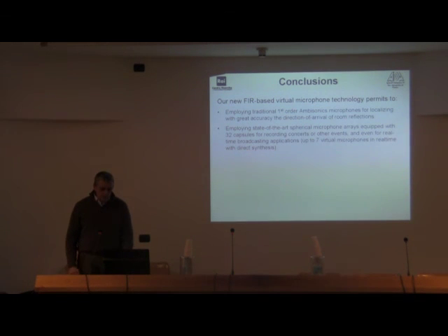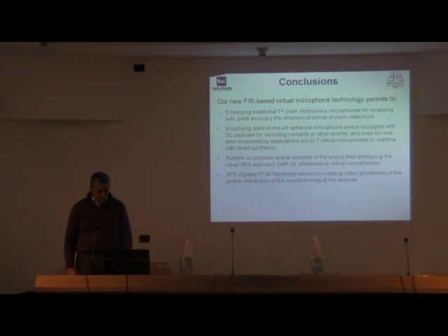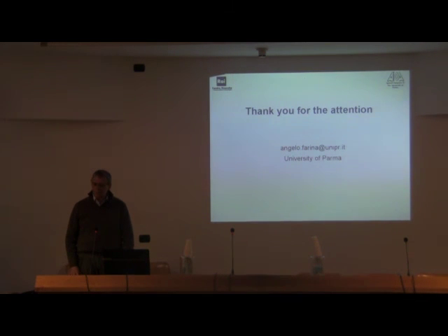Conclusion. Our new FIR-based virtual microphone technology creates very good super directive microphones, very nice for broadcasting applications. And we can move them in real time following the actor on the screen or something like that. We can make a complex spatial analysis of the sound field employing this novel SPS approach with 32 ultra-directive virtual microphones, and this allows for spatial analysis of the room reflections inside a concert hall. It also allows for very easy spatial sound reproduction in a three-dimensional loudspeaker array. Thank you.